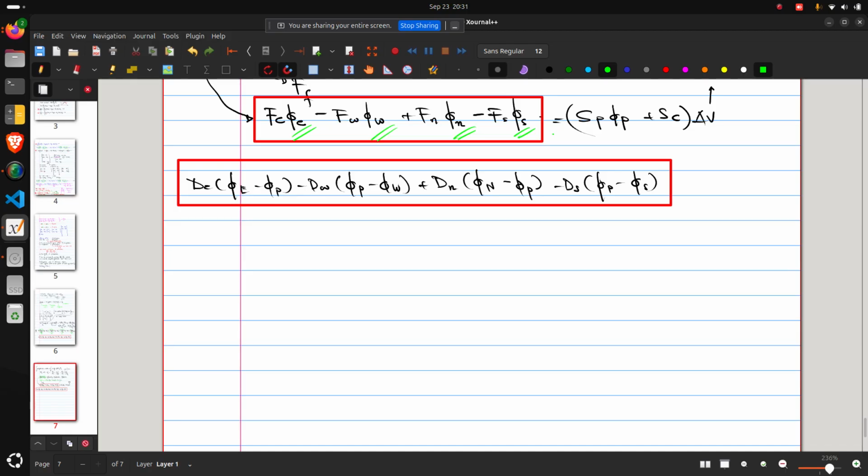So here we had done a linear approximation, right? Linear, that phi varies between two cells in a linear manner, and here we will take an average approximation, that the phase center value is nothing but the average of the two cell center values that the phase is sharing.